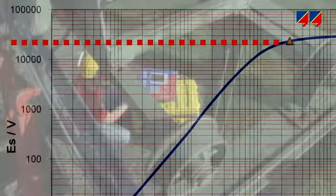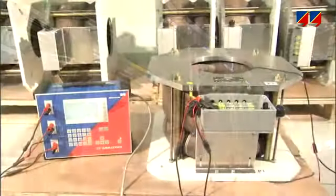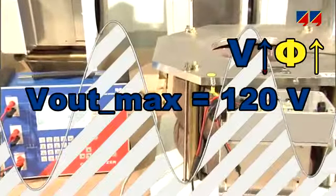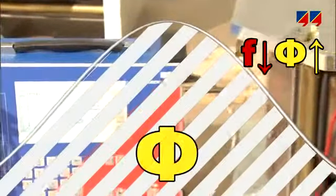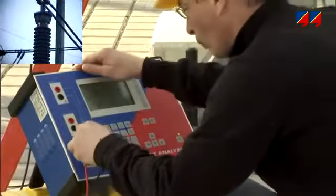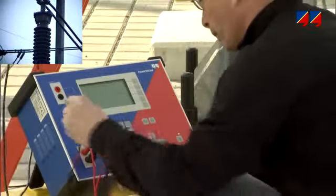CT Analyzer is a perfect instrument for measuring special purpose CTs with knee point voltages exceeding 10 kV, such as those used in generator, transformer, or busbar differential protection. It measures the excitation curve with safe low voltages of up to 120 volts and reduces the frequency if higher magnetic flux is required. Use of variable frequency and frequency selective measurement suppresses the electromagnetic disturbances in a high voltage substation or power plant for the ratio measurement.